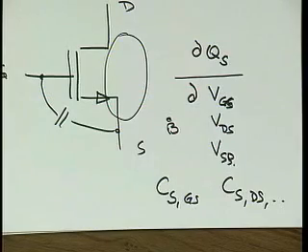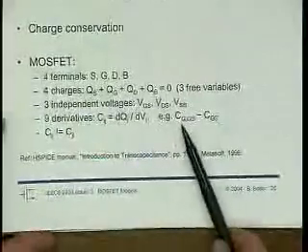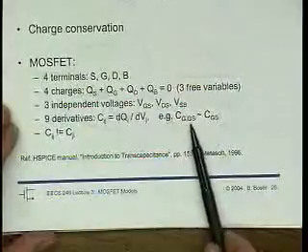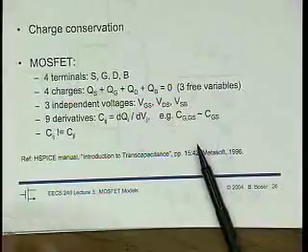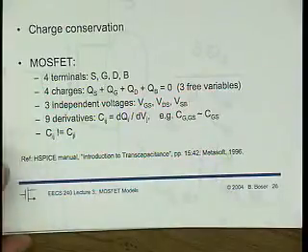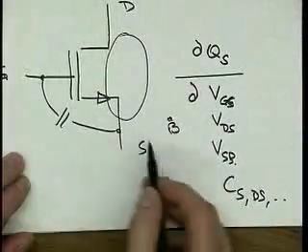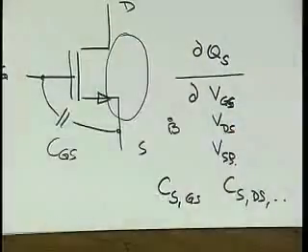And then you sort of can say that, well, the charge at the gate, its derivative with respect to VGS is about equal to CGS, so I want to call this CGS. Yes, you can do that, right? And then you map to these capacitors that we have. But it's really not accurate. And if we stick with this model of modeling capacitors like CGS, instead of really taking care of the charges, then we run into a big problem.